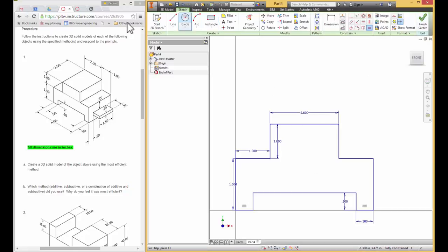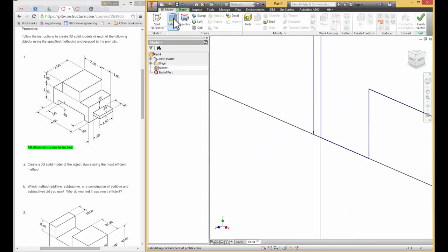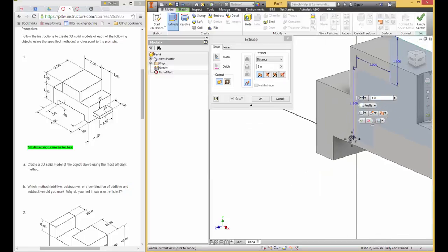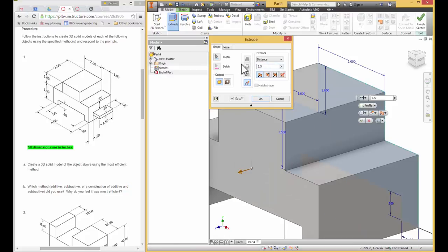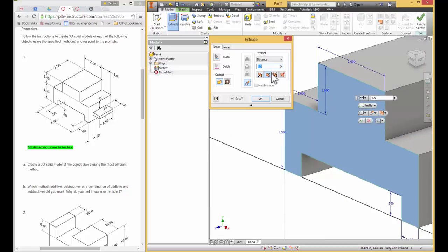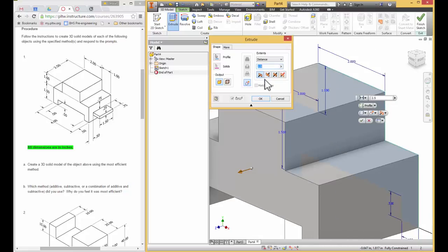If you want to click that, you can, or you can come over to 3D model, and we want to extrude. Now notice that it zooms, I'm zooming out and moving it where I can see. What is the distance we want to, the depth we want to extrude? Over here it's at 2.5. So I'm going to change that distance to 2.5, and we could actually go forward. We could extrude it back. We could extrude it to where we have half and half in front or back, or we could do asymmetric. I'll just leave it, the default is to make it go forward.